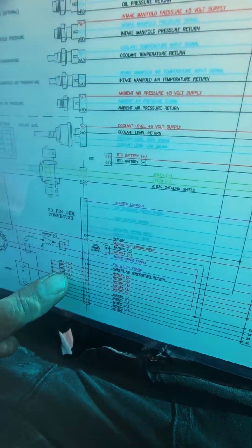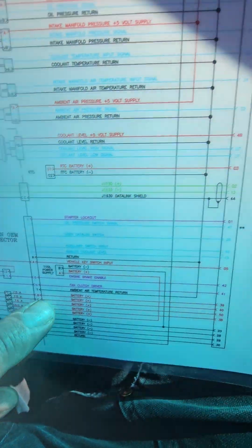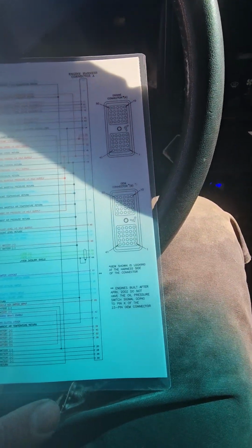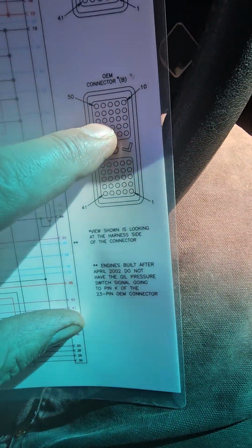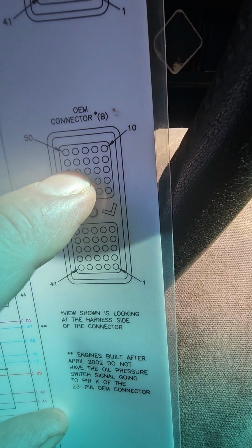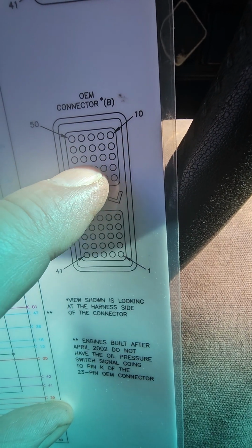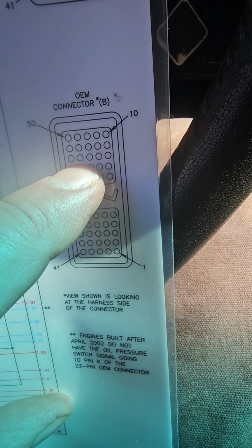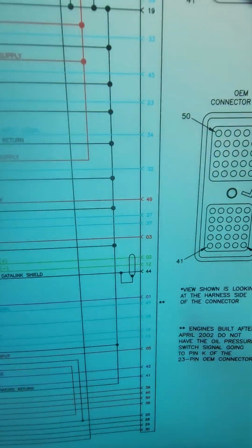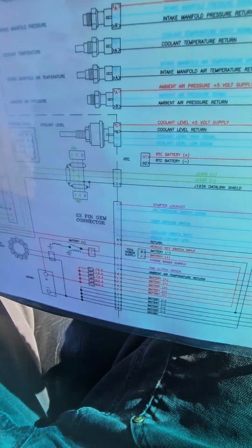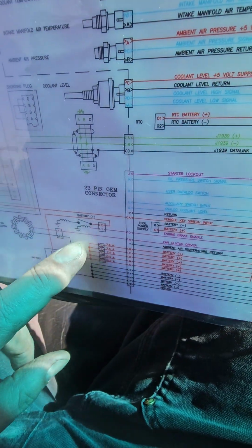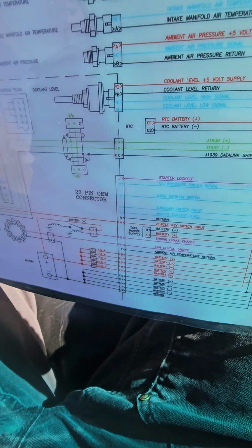And while we're at it, these fuses here, numbers 38, 39, and 40, these three had no voltage going to them, no battery voltage whatsoever. I've triple checked with the manufacturer. This is the correct schematic, but something's going on. So I'm going to set up the job site, and then we're going to figure out what the hell's going on and probably end up doing some rewiring if I can't find the problem in the fuse section. And that's it for now.